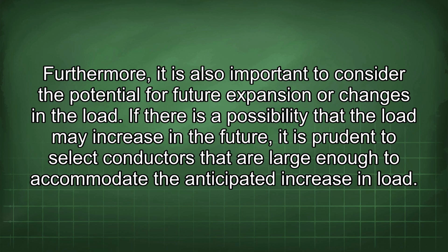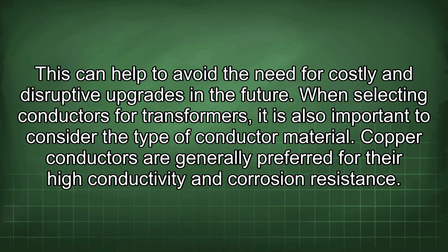Furthermore, it is also important to consider the potential for future expansion or changes in the load. If there is a possibility that the load may increase in the future, it is prudent to select conductors that are large enough to accommodate the anticipated increase in load. This can help to avoid the need for costly and disruptive upgrades in the future.